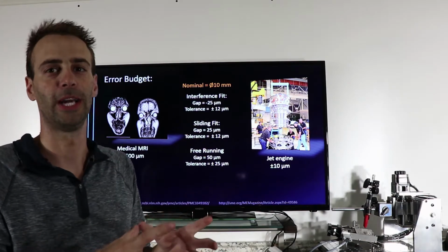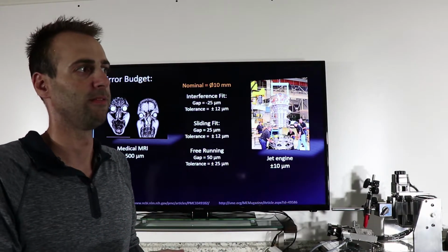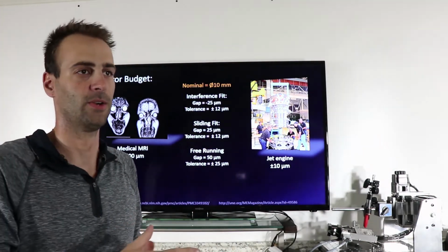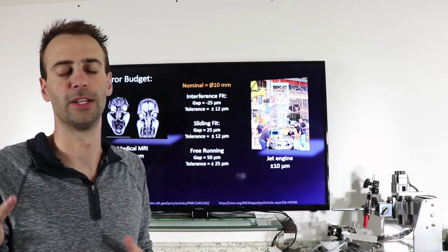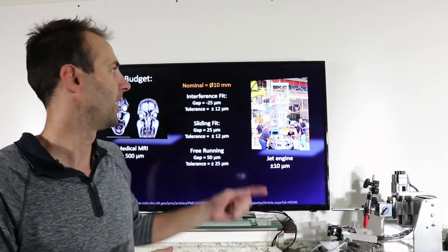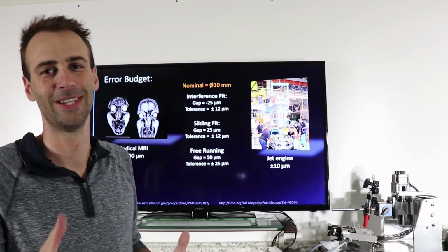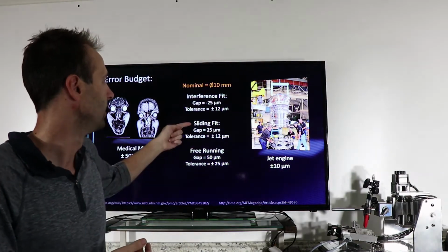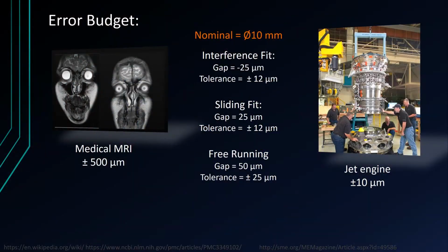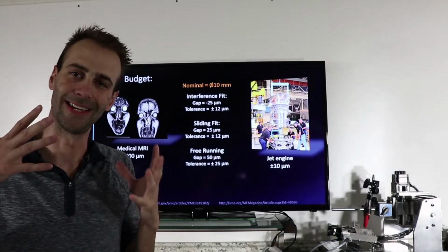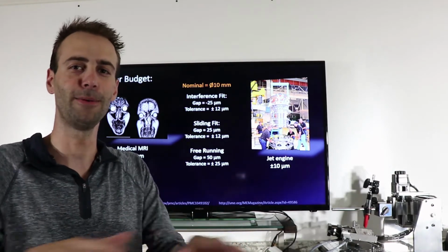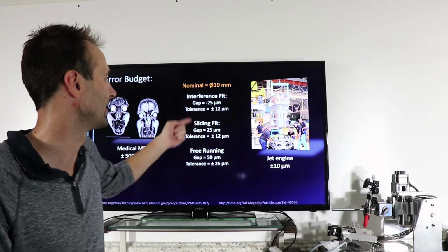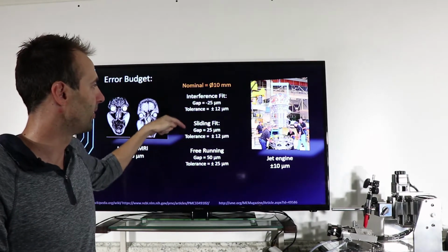So when I make that shaft, I'm shooting for a 1/2,000th over, or 12 or 25 microns over, or whatever. Call it 12 if you want to split the difference. But I also have a tolerance of 12, so it's about a 1/2,000. This is probably as tight as you want, and think about that. That's a locating fit, for engines and things. People at home are probably not going to be making anything more precise than this. So you're going down to a relaxed fit.